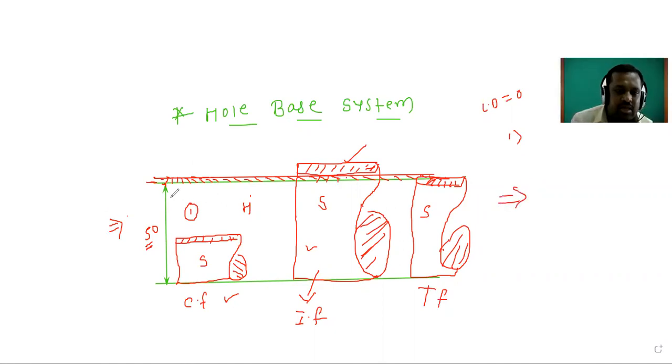Here we have varied the size of the hole? No, we have not varied the size of the hole. We have not varied the size of the hole to achieve the different fits. We just have to change the size of the shaft only.